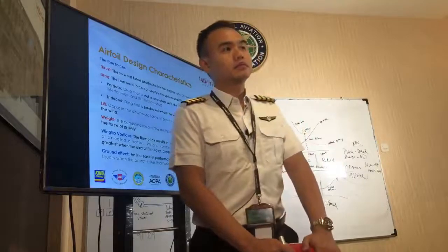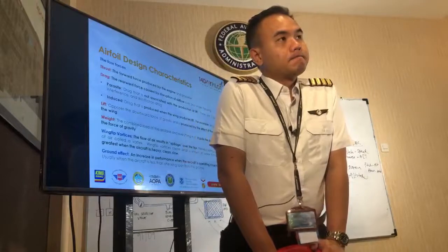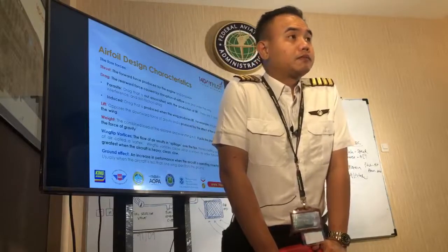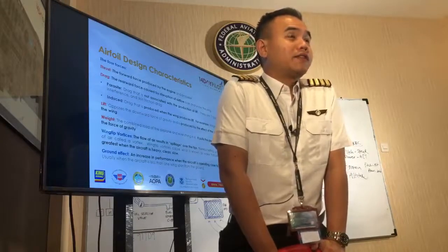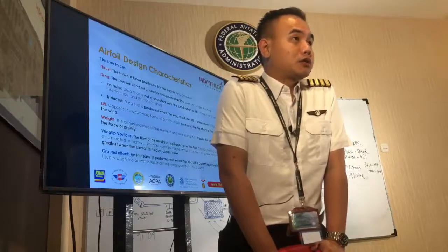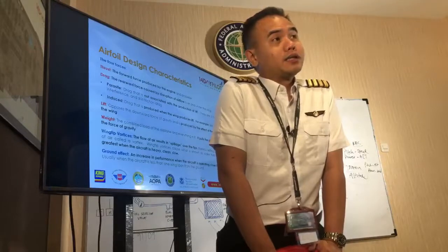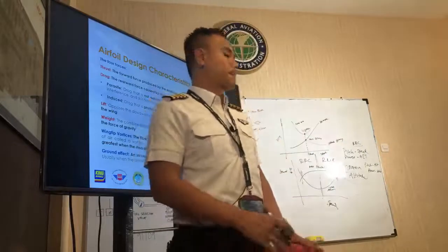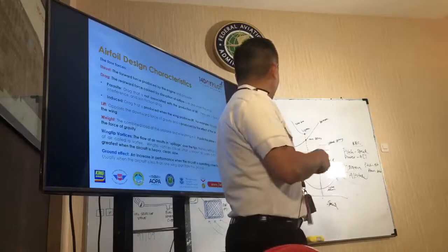Oh, this one is 61 with flaps up, but with flaps down it's 60. Is it that different? Yeah, because you have a little bit of extra lift. Because if you fly at 65, and at 60 you have flaps 10, then you can fly at a lower airspeed. Then the configuration changes. Okay, so that's about the drag.